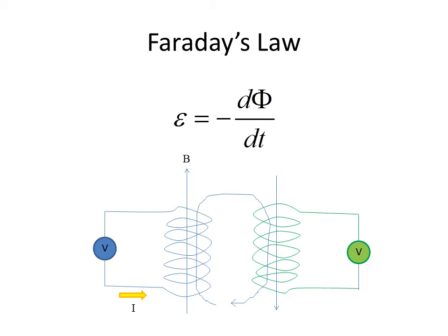the second set. Now, if that magnetic field is increasing, the second set of coils will try to oppose that change in flux by generating its own magnetic field in the opposite direction. Once again, using the right-hand rule and noticing that these coils are wound clockwise as you go up toward the top of this image, we can determine the direction that the current must be flowing through the second set of coils in order to generate this magnetic field.